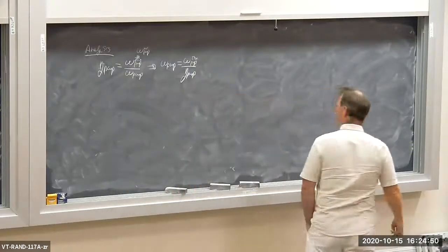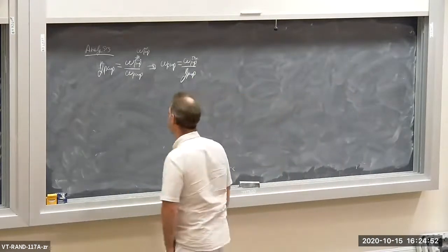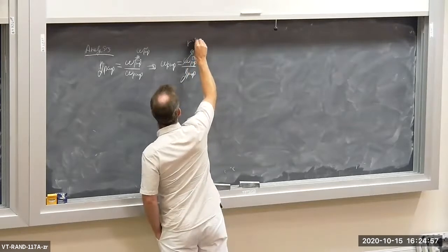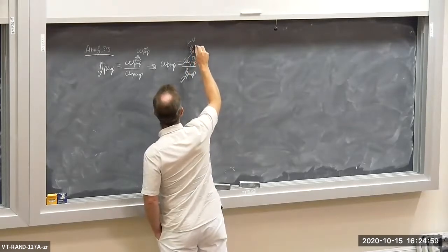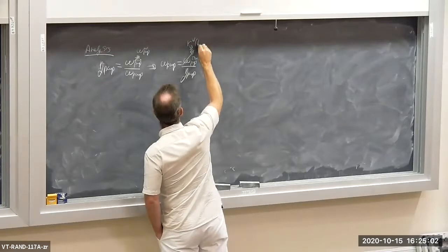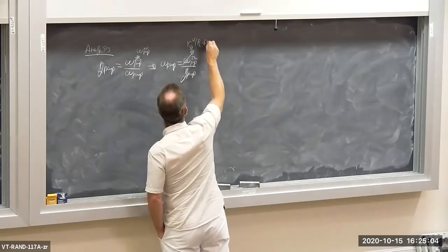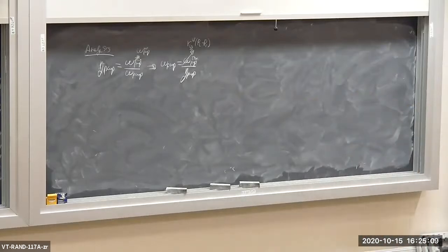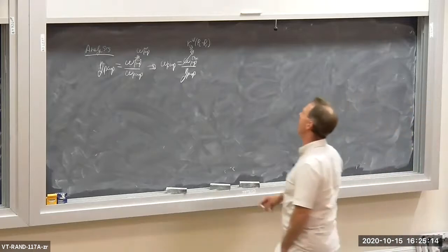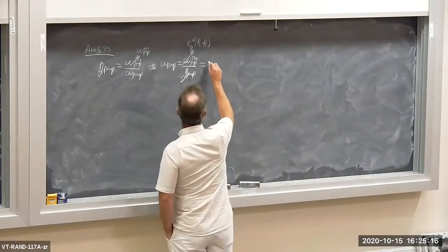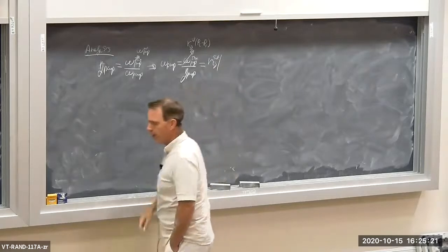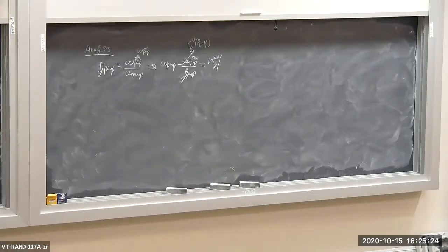Now, we already have an expression for the isentropic pump work. We developed this last time. That's the specific volume of the saturated liquid times the delta P, so that'll be P2 minus P1. We developed that expression for isentropic or reversible pump work, if you like. So I have a specific volume of the saturated liquid evaluated at pressure P1.